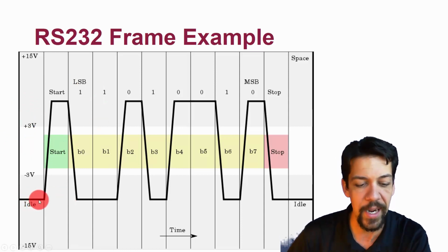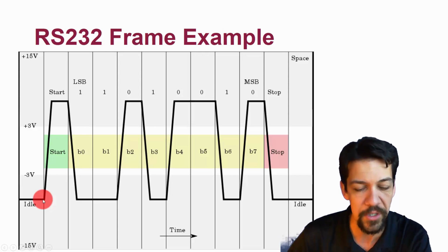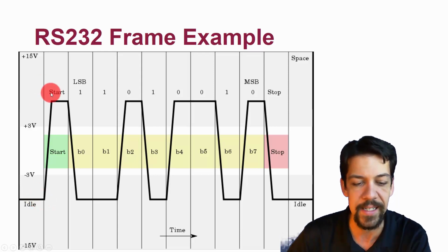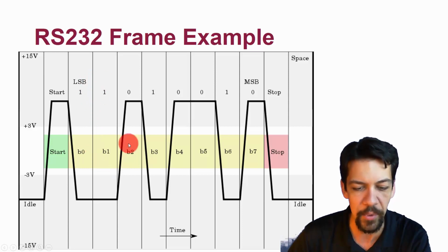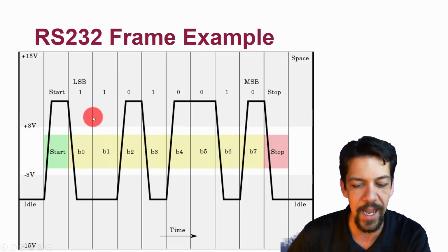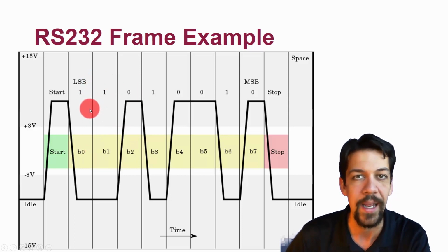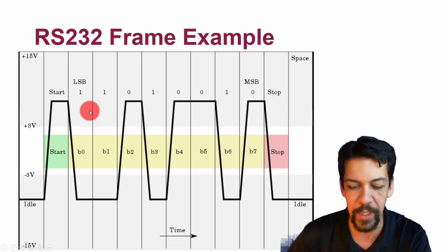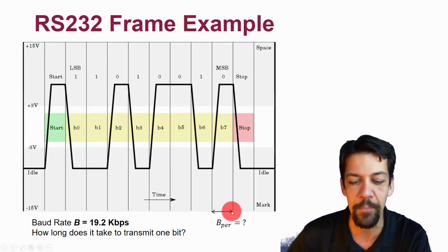So it starts out idle, which is the low voltage state, or all ones. It sends a 0 start bit, and then each of these bits is sampled on these sample ranges here. Both processors have to wait a fixed amount of time between the two bits, and this is the bit period.